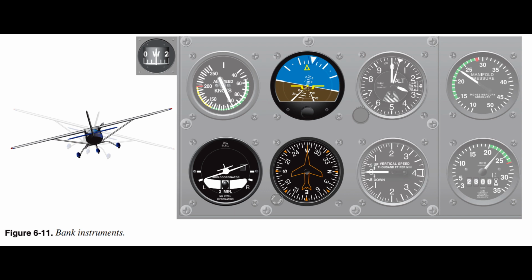Care should be exercised when using the magnetic compass as it is affected by acceleration and deceleration in flight caused by turbulence, climbing, descending, power changes, and airspeed adjustments. Additionally, the magnetic compass indication will lead and lag in its reading depending upon the direction of turn. As a result, acceptance of its indication should be considered with other instruments that indicate turn information. These include the already mentioned attitude and heading indicators, as well as the turn and slip indicator and turn coordinator.